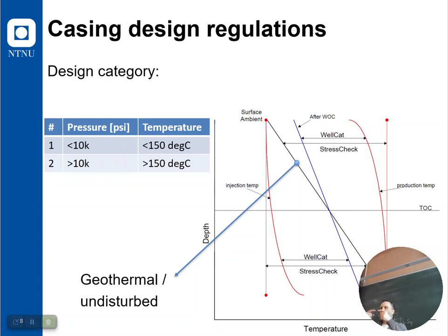During summer, they are almost together. A bridge always has something at both ends. It does this according to the temperature. When it's cold, it contracts. When it's warm, it expands. Even concrete does this. The steel is actually very much alive, temperature wise. You heat it up, it gets longer. Okay, so a steel rod, and the well will do that too.